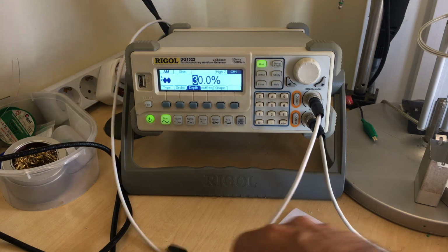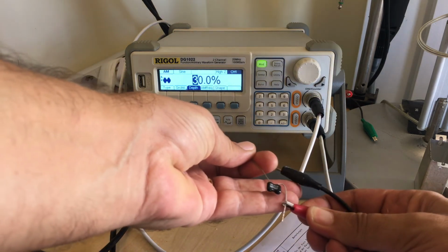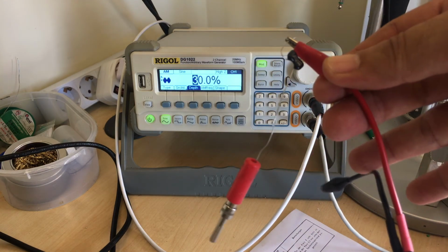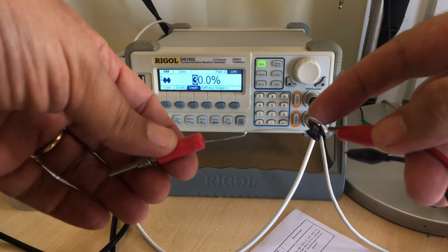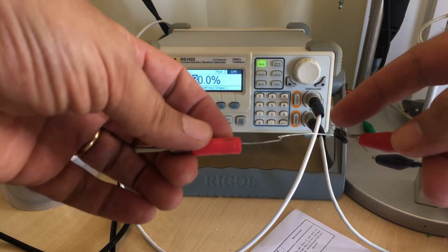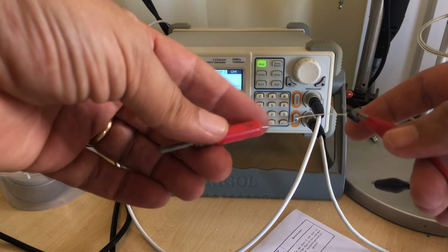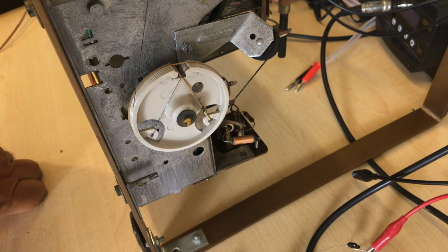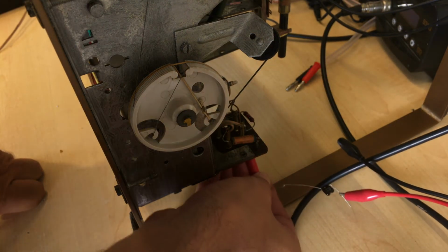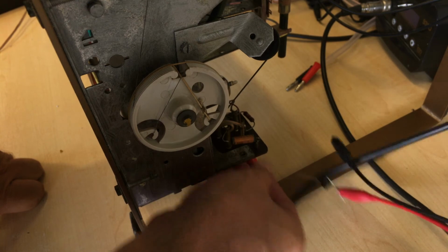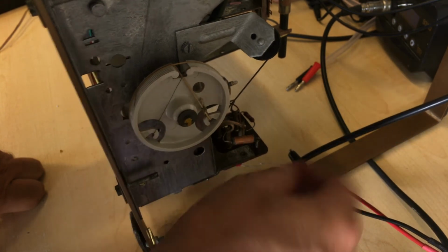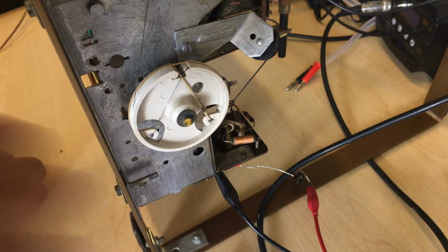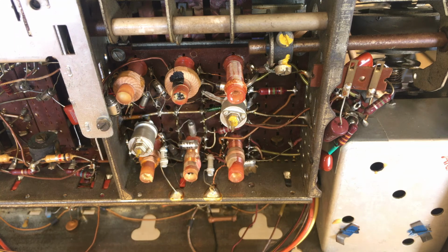And what I need to do now is feed it through a dummy antenna. Now the dummy antenna, according to instructions, is simply a 220 picofarad capacitor in series with a 220, I believe it is, ohm resistor. That's going to go into the antenna socket. So I'm going to put that into the AM antenna, the external antenna socket. I'm going to connect the ground of the signal just to a convenient chassis ground point.